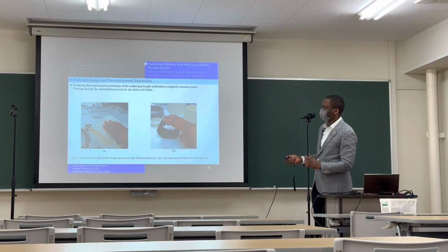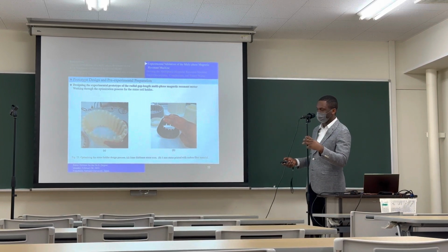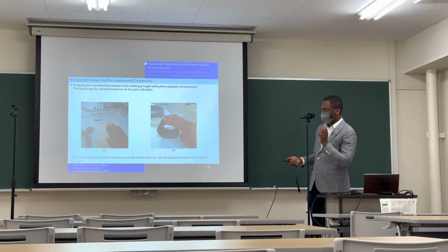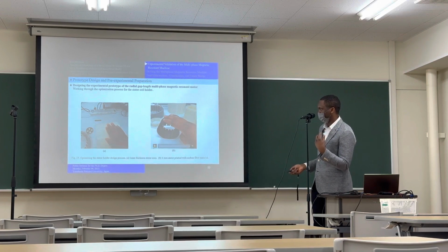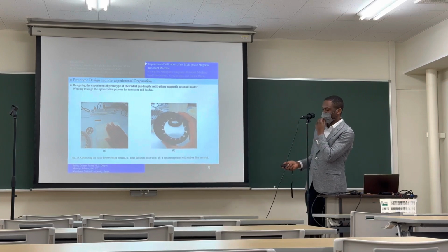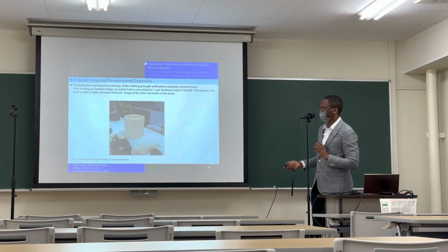And throughout the years, while doing multiple printing and multiple testing, we realized that we can create a sort of stator holder that will hold the main coils on the stator, and then we can place that stator holder inside the main stator. For the stator holder, we realized that if we use the 3D printer plastic with 1 millimeter of thickness, it becomes flexible, like you see here. We tried different designs and realized this was flexible. So with this flexible design, we designed the main stator coil holder. It will hold the stator coil in place, and then we can do whatever we want with the coil.